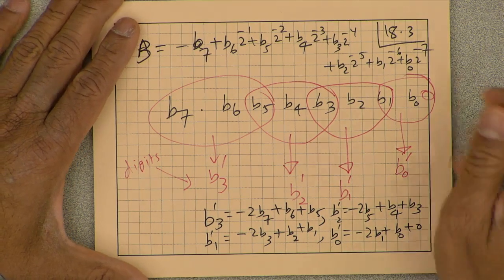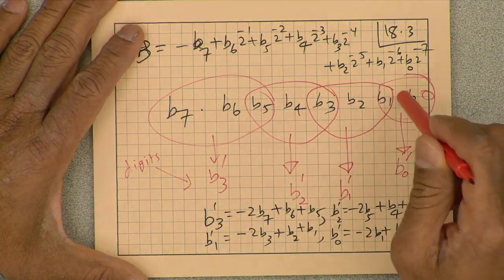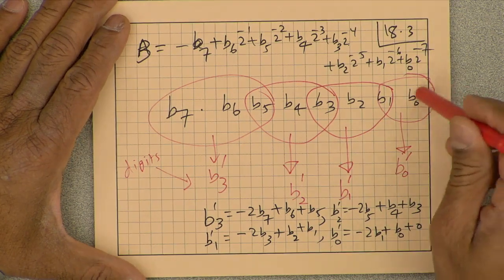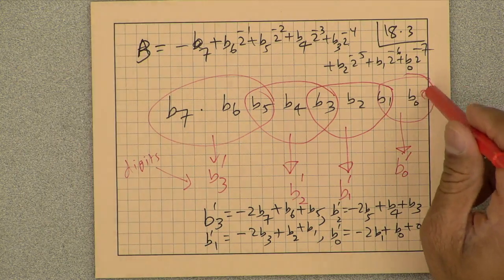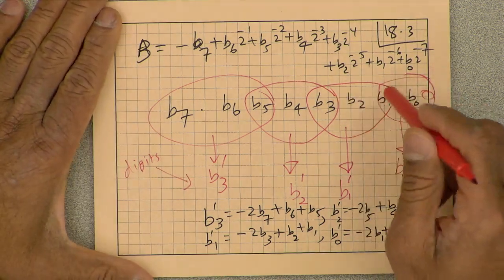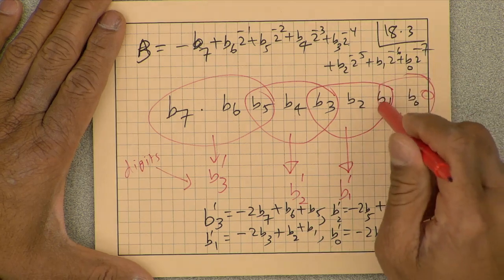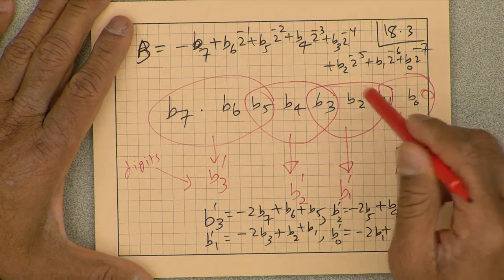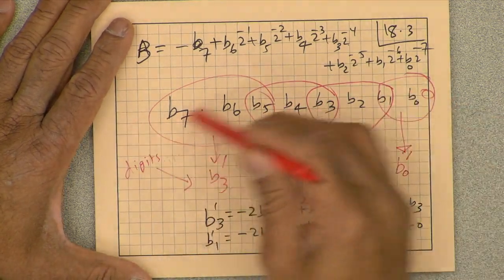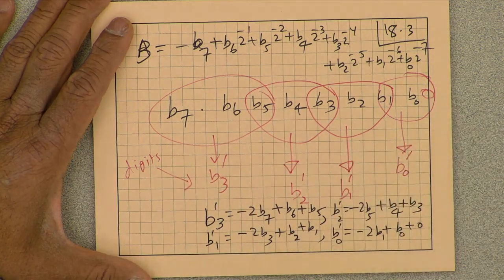In general, if we have a W-bit number, we append a 0 at the LSB position, and then keep taking groups of 3 with one overlap from the previous digit and 2 new bits, one overlap, 2 new ones, like that. By doing that, we can take a W-bit number and create a W by 2 digit number.